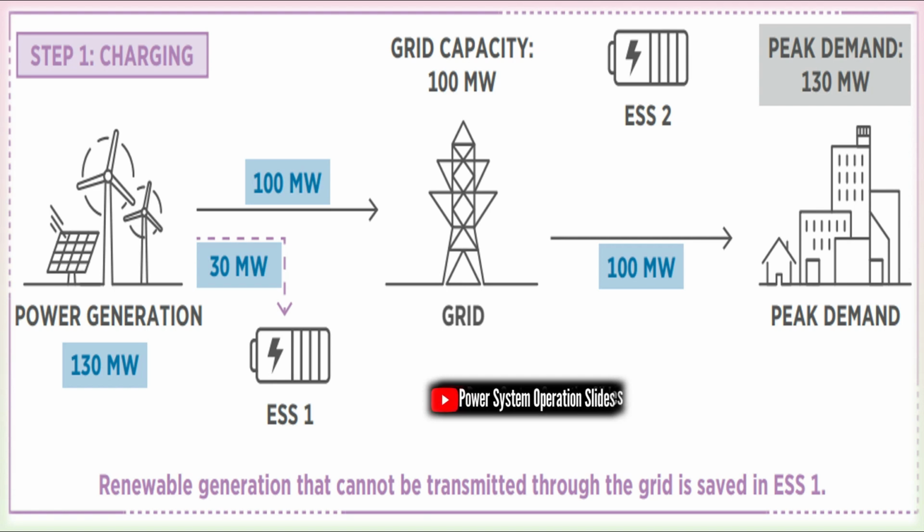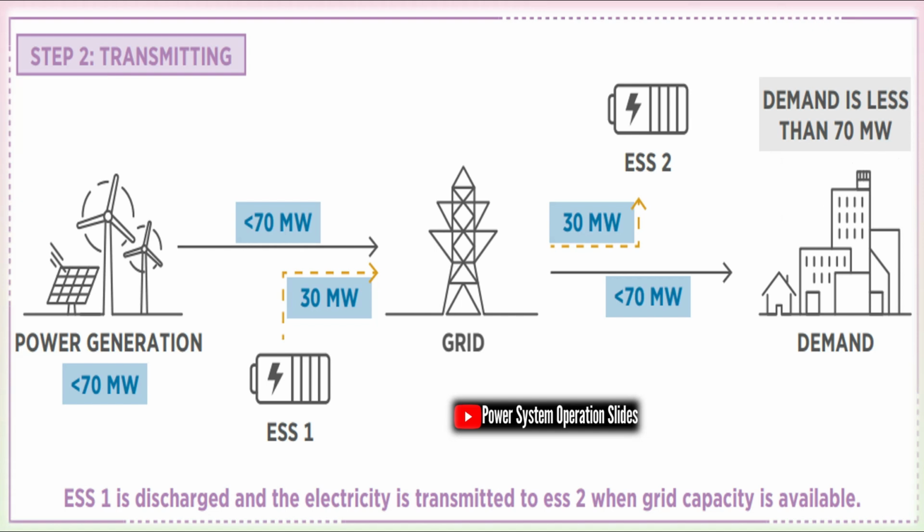Detailed procedural steps to implement a VPL project, the lifecycle. Assessment and feasibility: perform power flow studies, contingency analysis, and economic assessment to identify bottlenecks and candidate nodes for virtual transfer. Identify available controllable assets: BESS, FACTS, DERs, flexible loads. Functional design: specify control objectives, such as increase transfer by X MW for Y hours, provide congestion relief, or provide reserve.